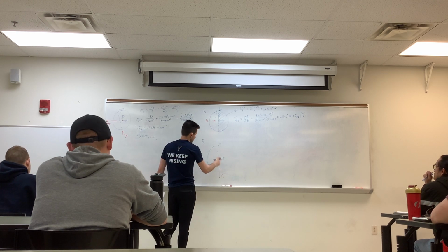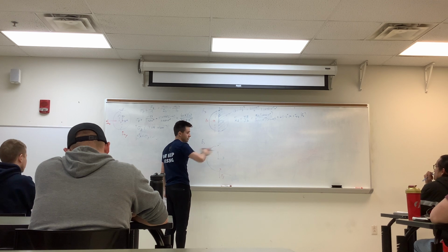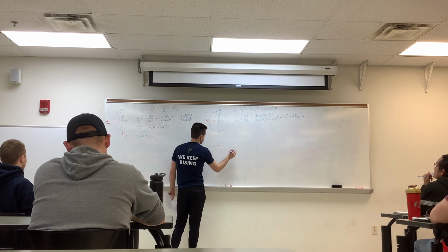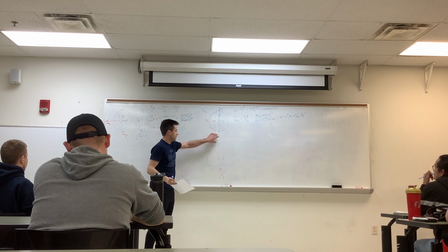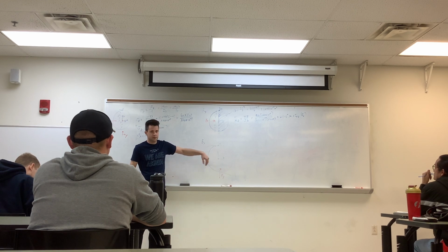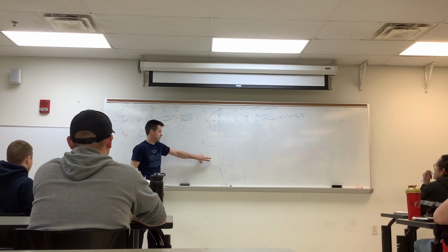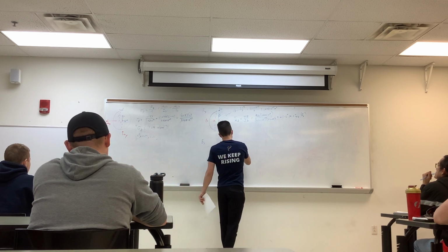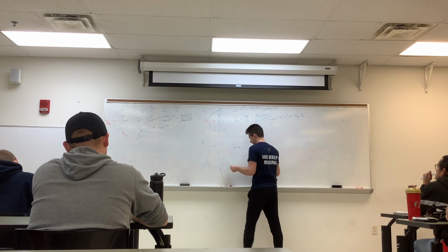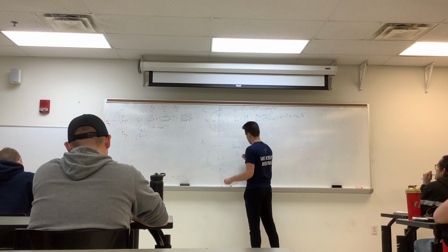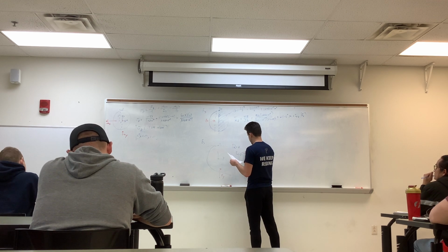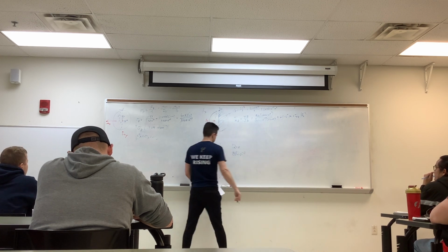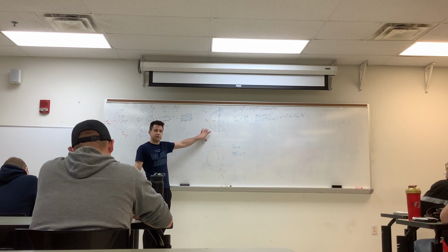So this one, which is interesting, when we do our shear analysis, we take a cut on our area of interest. So here it's going to be point H. But with this one, you either cut off nothing or the entire thing. So your shear flow will be 0, giving you 0 shear stress with regard to Fy. So Q is 0, giving us tau yz is equal to 0. And this is with regard to force in the y.